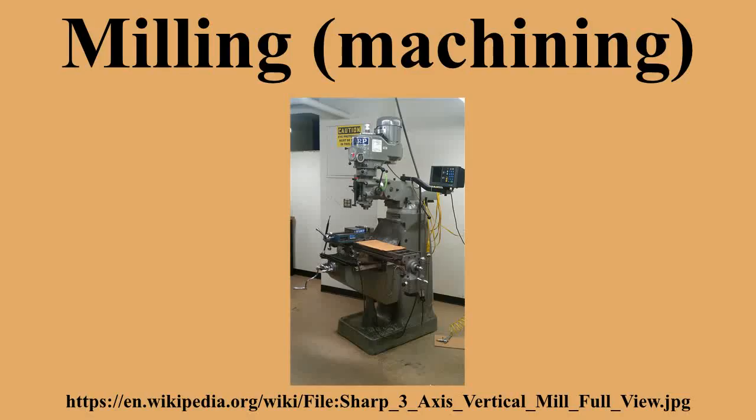For manual milling machines, there is less standardization, because a greater plurality of formerly competing standards exist. Newer and larger manual machines usually use NMTB tooling. This tooling is somewhat similar to CAT tooling but requires a drawbar within the milling machine. Furthermore, there are a number of variations with NMTB tooling that make interchangeability troublesome. The older a machine, the greater the plurality of standards that may apply.